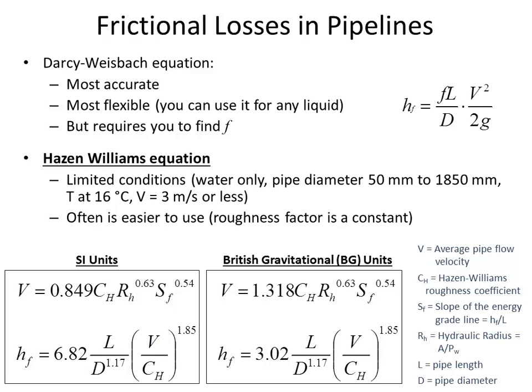There will also be the velocity head to take into account, but sometimes you know the head loss, and you want to find what will be the velocity through the pipe in response to that. So that if we had a higher tank, of course, the velocity is going to move faster. If you elevate the tank, the C value won't change. The hydraulic radius won't change. But what will change is the S sub F.